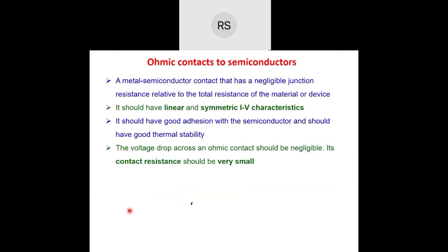Okay, so you see, if there is a device in a semiconductor, what happens? Whenever there is a junction, what do we mean by junction? Junction means there are two different regions in a semiconductor, and there is a potential barrier existing at some interface. This potential barrier gives rise to non-linearity in the IV characteristics, which we call rectification. It is given by this barrier existing at the interface, whether it is a PN junction, a heterojunction, or a metal semiconductor junction.